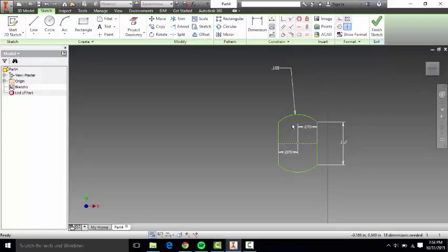Now I know this is a radial dimension based on the way the arrow is pointing at the circle. We'll see in a second what a diameter dimension looks like. So if I go to the circle tool and create a circle with a radius of 0.105 or a diameter of 0.105 times 2, we have our base circle.